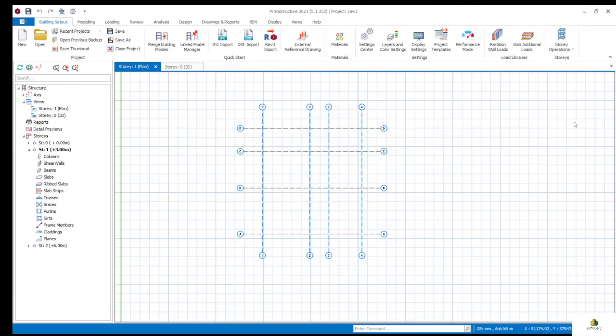And there's one thing that I want to talk about. Let's go to the edit story. Let's say you want your columns to move throughout the building, right? What you do is click on the edit story, then you see the edit story dialog box. On the table at the far right, you see similar stories. What you do is at the first story, where the similar story is, click that place, then you hold shift to drag it down to select all the stories that you want.